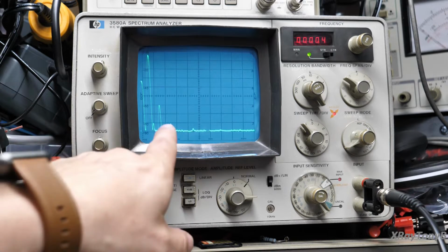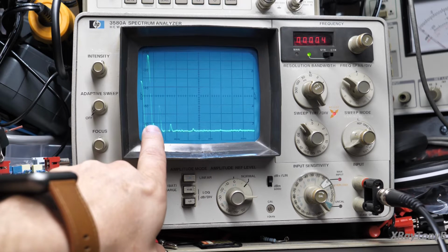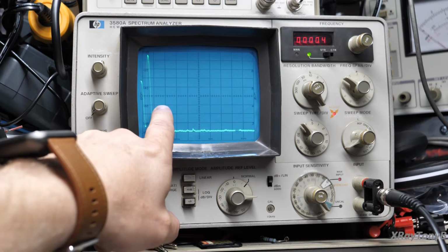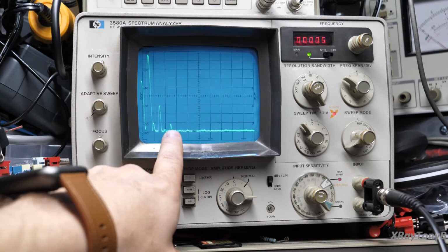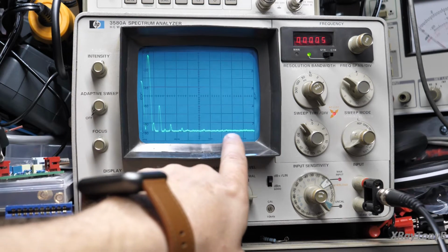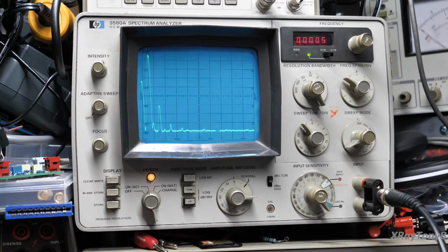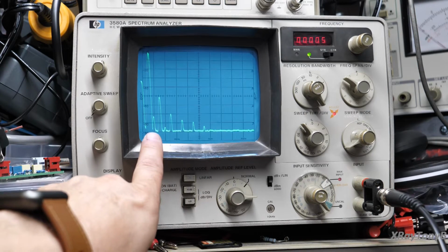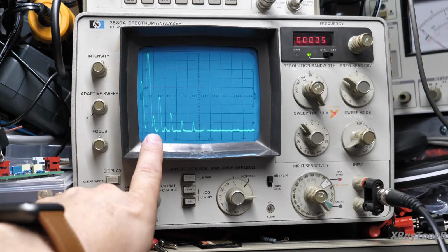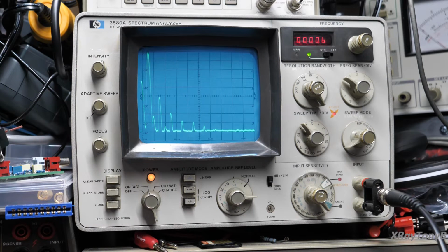If we go up to our 60 watts, you can see we now have something here, and our second harmonic is much higher. Now we have a third harmonic, and then some other little ones, so you can see that's where that 0.1 something % is coming from. And if I run this up to the 108 watts, you can see there's quite a bit in here. We'll do one more sweep. And you can see there's quite a bit of distortion showing up. Multiple harmonics.